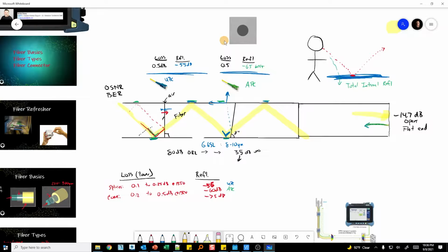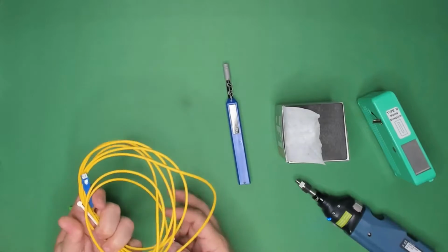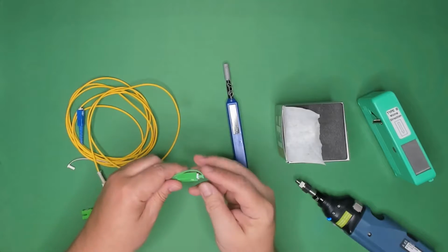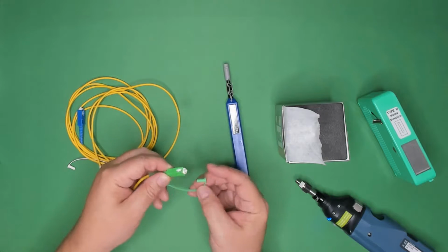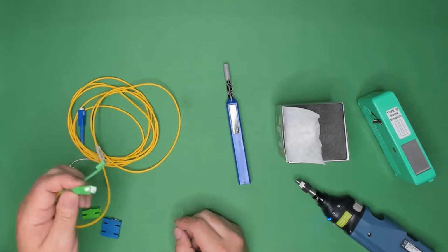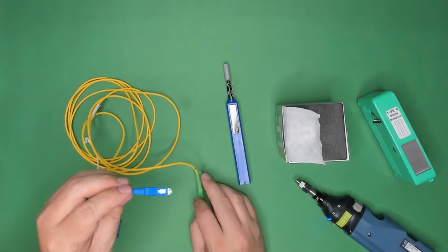And so from this point, understanding the different types of connectors really does become important, because if you start looking at systems that have different types of connectors, right? We talked about these 2 different kinds of connectors out here. So the green connector here is APC, or angled physical contact. It'll be hard to see here, but there is an angled, or 8-degree, cleave on this connection. So you must plug a green into a green. You should never plug it into a blue connector. You can damage it, all right? So that's very important to understand. And then, of course, you have the UPC here, right?